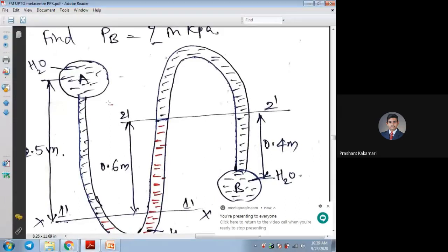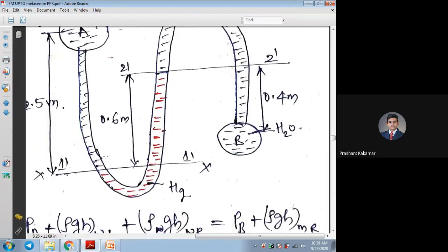If atmospheric pressure were acting on any side of the pipes, then we would have added that atmospheric pressure, and that would become absolute pressure. Is that clear? As those pipes and the U-tube are all connected to each other with respect to inside pressures, without being exposed to atmospheric pressure, that's why we are calling it gauge pressure.